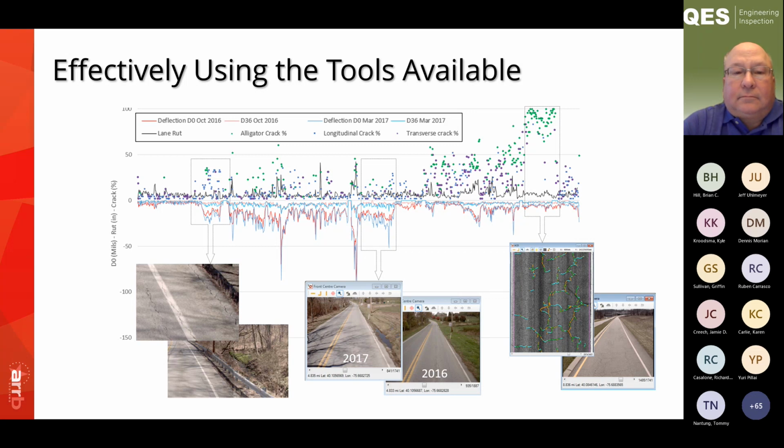So, we're really trying to see beneath the pavement surface to identify areas of concern before they propagate to the surface. And then the example on the far right is the other interesting extreme, which is when it looks horrible from the surface, but when you have all of the appropriate data, all the structural response information, quite frequently you discover that there's actually no structural problem. It's just a bad surface mix, and all you really needed to do was mill off the surface and replace it.